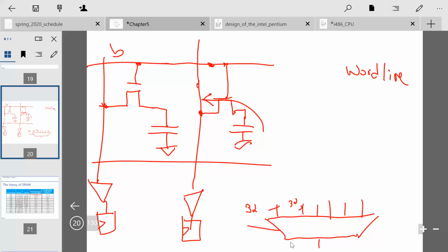It takes advantage of what the memory we fetch from calls burst mode. You pay a certain amount of time to access that first piece of data in the row, and after that, it's about a tenth of the access time to access each remaining piece of data in that row. With burst mode, the cache lines are lined up with the rows of the memory, so accessing a cache line takes a few cycles for the first word, and then pulling in the rest of the cache line is very fast.